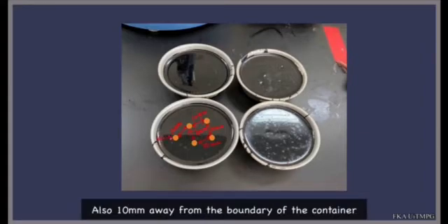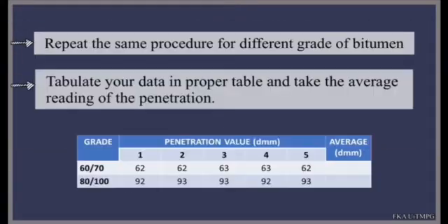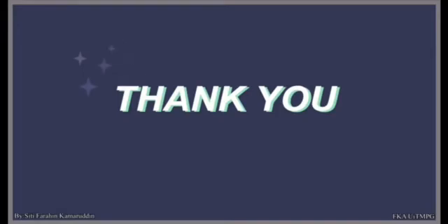Also, keep 10 millimeters away from the boundary of the container. Repeat the same procedure for different grades of bitumen. Tabulate your data in a proper table and take the average reading of the penetration.